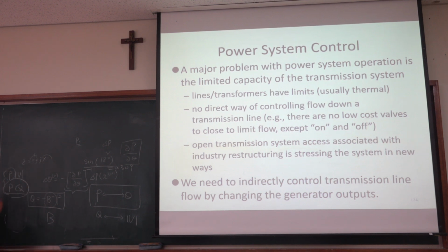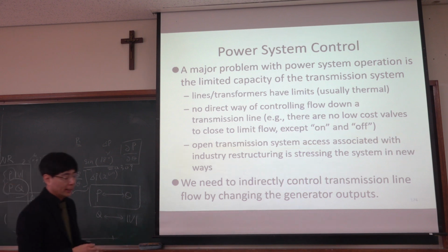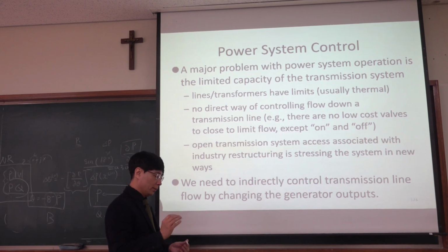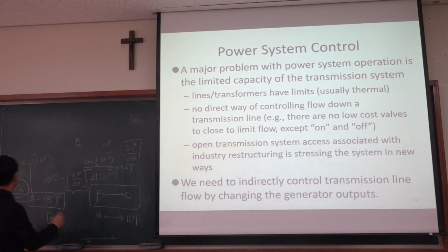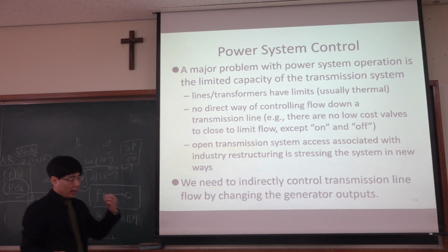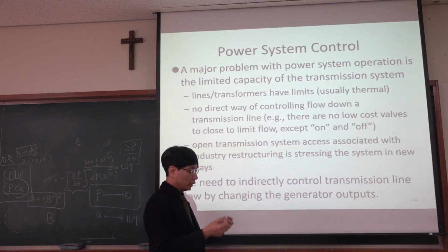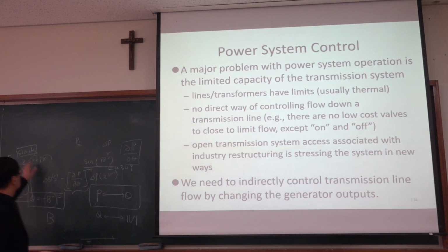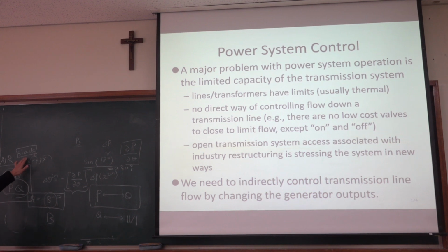There is no control part so far, Newton-Raphson. No control, just solving equations, given, just solve, and then power flows, and then we can satisfy the customer's requirement. And anyway, we have a slack bus, so the required active and reactive power can be supplied from this slack bus anyway. Then what is missing here?